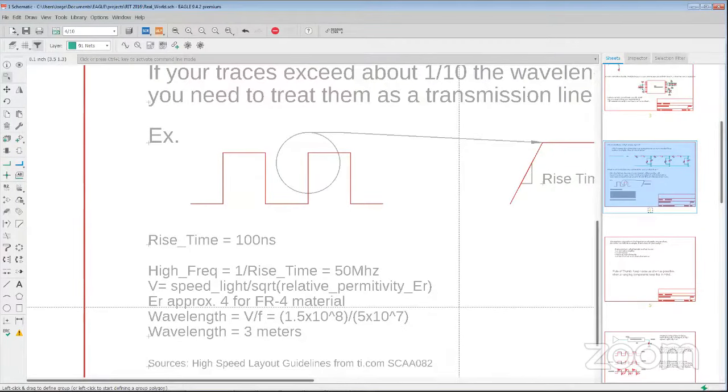So what we see here is we can make the basic assumption that we have FR4. If you are doing super high speed stuff, you will likely be using different materials that are tailored specifically for the application. But just to get some numbers, to get some intuition, FR4's relative permittivity is 4, hence the name, I think. I don't know exactly if that's why they named it FR4, but it's a good way to remember it. So as we can see, square root of 4 is 2. So the speed of propagation in a circuit board is half the speed of light, roughly.